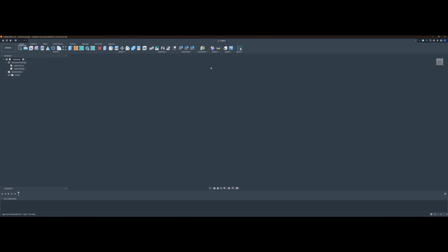To start the add-in, first make sure you are in the Fusion 360 Solid workspace. If the command icon is visible on the toolbar, you can launch it directly from there. Alternatively, go to Create and the pulley generator should appear in the list. If the add-in is not on the list, it is probably because it is not running.